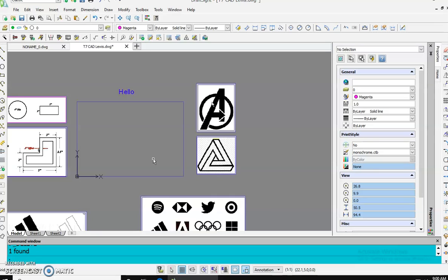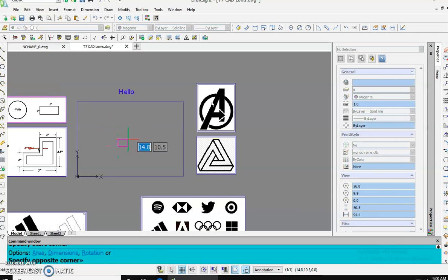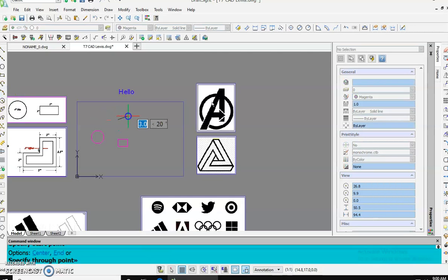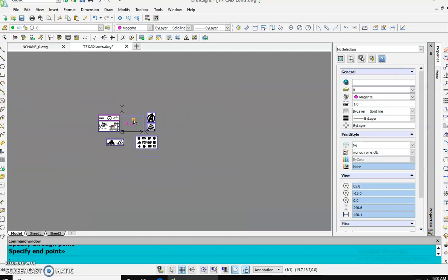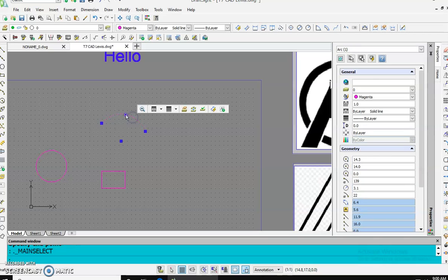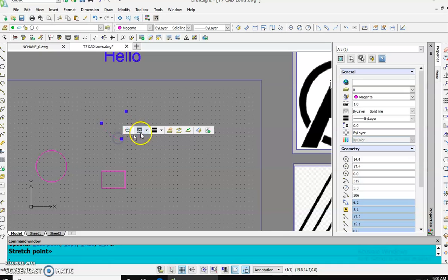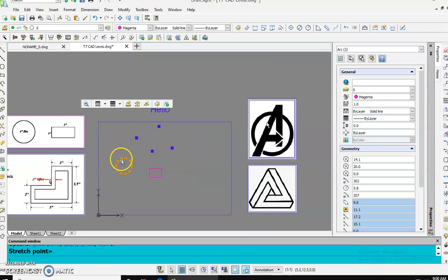So we're going to conclude this first video just to keep you acclimated. Go ahead and draw whatever you want with your lines. Try out the rectangle. Rectangle is just as easy as a line. It's 2 dots, 2 points of reference. Click, drag, click. Circle, click, drag, click. And then you have an arc, that's 3 points of reference. Click, click, and then click. And again, same thing. Anytime you click on one of these points, you can adjust the different angles and radiuses, and it's really easy.